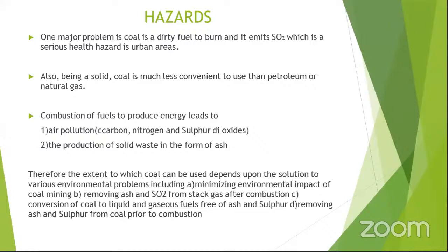So to dispose of the fly ash and pond ash was a very huge concern till 10 or 15 years ago. But now this fly ash and pond ash have been incorporated in concrete production. Okay, because fly ash exhibits properties which are very familiar to cement. Okay, they also have a cementitious property which will bind the material. Therefore, the fly ash is being used in cement production, and pond ash is used in concrete production, and that's how the solid waste from the thermal power plants is being disposed of.